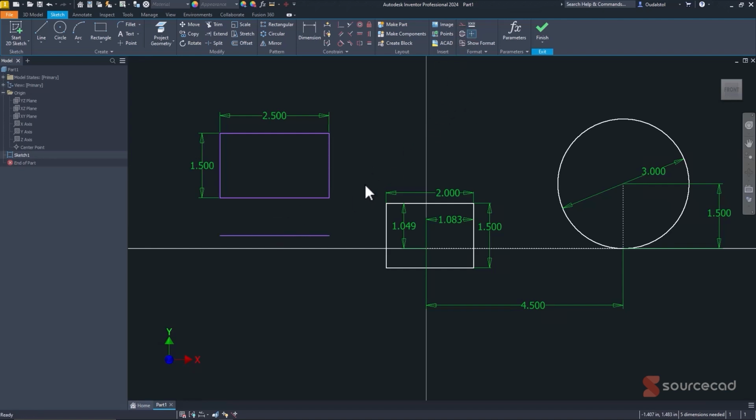But if I dimension from this one to this one, it's like I said, a 1.5 inch diameter of this cylinder I'm going to make. I can make it a little easier for myself, and personally, I like to use the numbers I'm being given. So if I select this line, there's another type that's called center line.